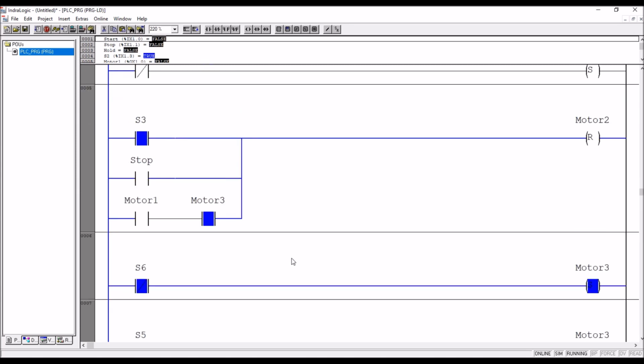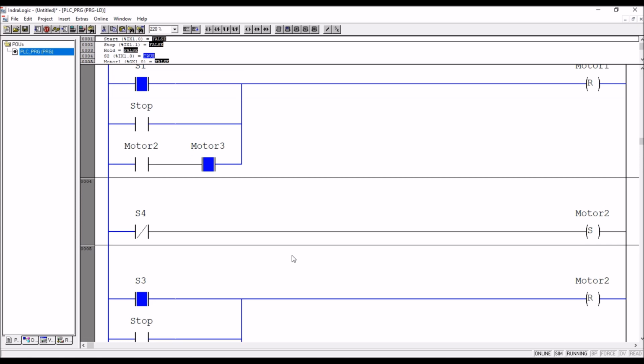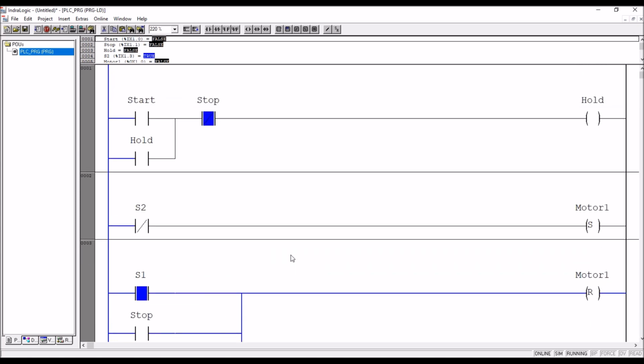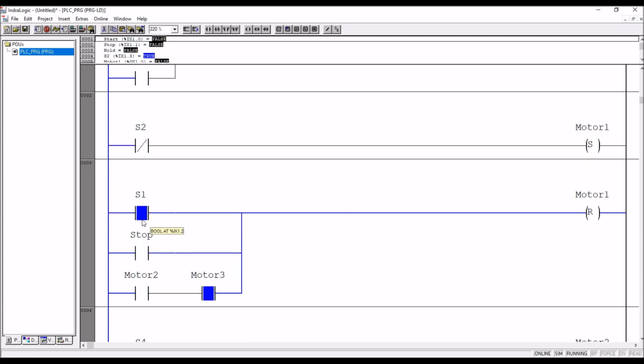By chance, say for example, tank 1 got empty. Tank 1 empty means what? Go to tank 1. Tank 1 empty means what? First the high level sensor will be off. When tank 1 is really empty, the low level sensor will be off.